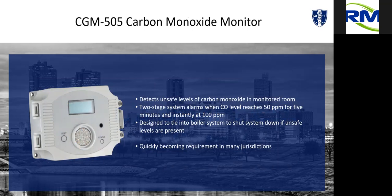It's a 2-stage CO monitor. It's really specifically designed for the mechanical room because it has appliance interlocks where we can tie in either to the appliance safety loop or through a general building safety loop, like kind of in series with like a punch switch or something that will solenoid valve close a gas valve or something like that. So if it ties into the draft controller, that interlocks to the appliances. That works that way. But it's a 2-stage system.